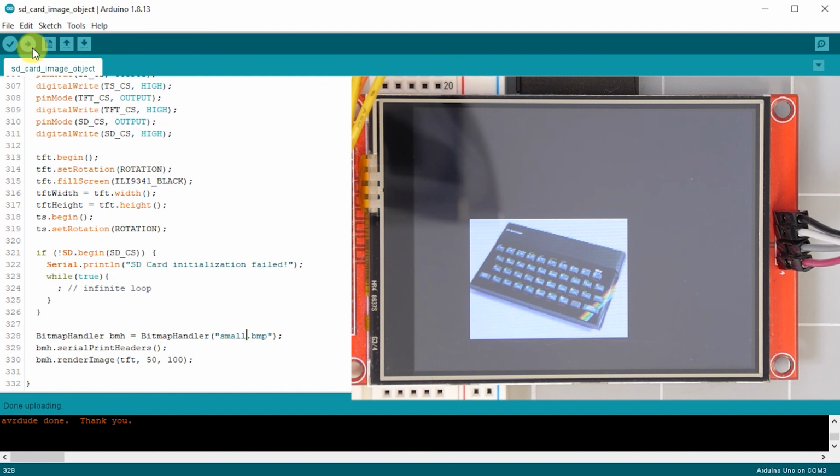So we've really now got a little library that lets us specify a 24-bit bitmap file, position it anywhere on the screen, and it will then be drawn either full size if there's enough room or clipped to fit onto our LCD screen. So we can use this now for positioning images around, maybe as an actual photographic background for our control panels, and on top of that we can then draw the needles for each of the dials and so on, or just some sort of decoration on our screen, or some splash screens, or whatever we want to do with that.